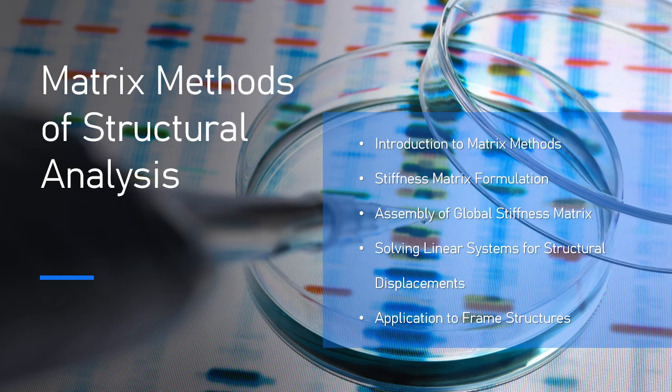A is the cross-sectional area. I is the second moment of area. L is the length of the frame element. This matrix considers both axial deformation and bending deformation and is commonly used for analyzing frame structures, e.g., buildings, bridges.